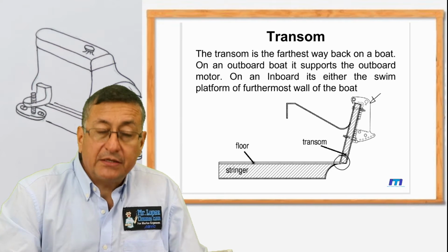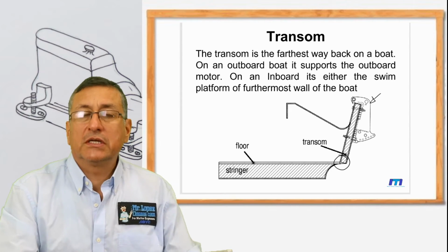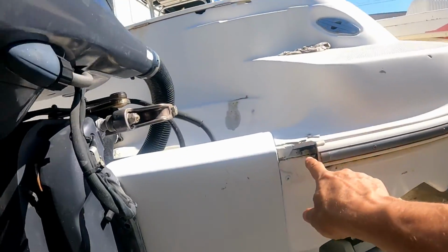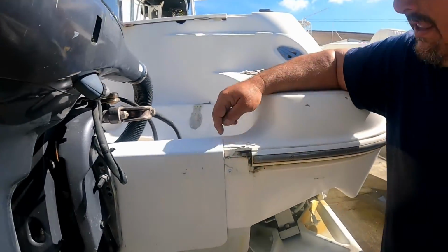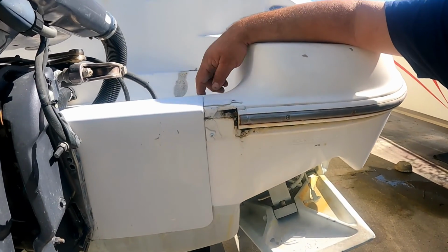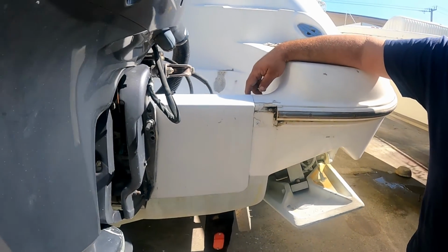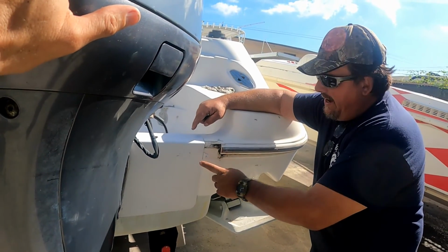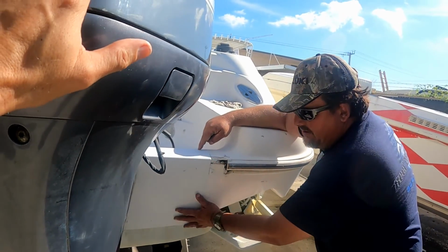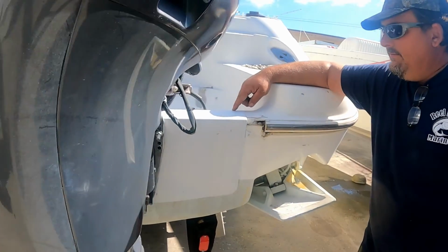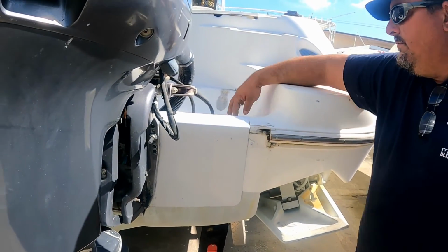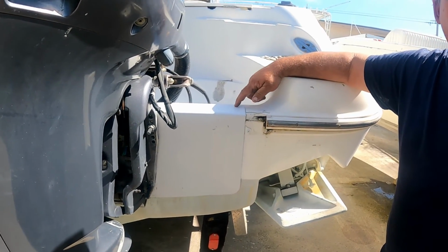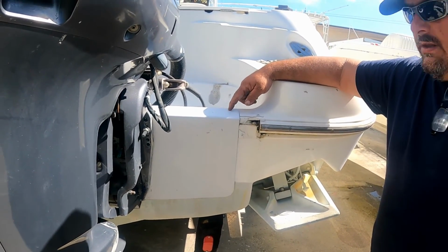Yes, there are companies that reinforce the transom with aluminum brackets. Look at this worst scenario, Danny. Wow. The water is penetrating in the transom, and probably this transom is full of water. Yeah, absolutely. With that open, not only that, they put a Band-Aid on it. They put this aluminum piece. This is cosmetic. This bracket is supporting, but it's provisional. Yes, that's a temporary fix. Correct. That transom is broken internally.